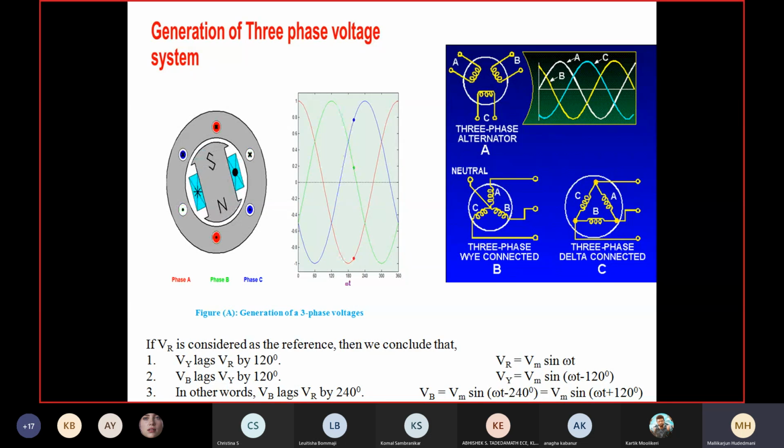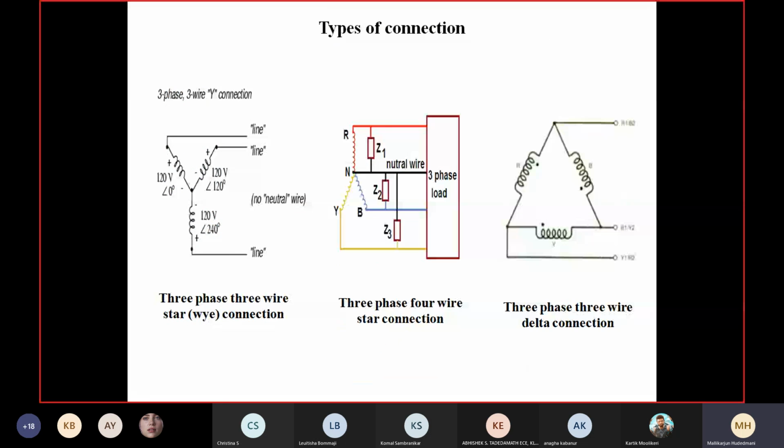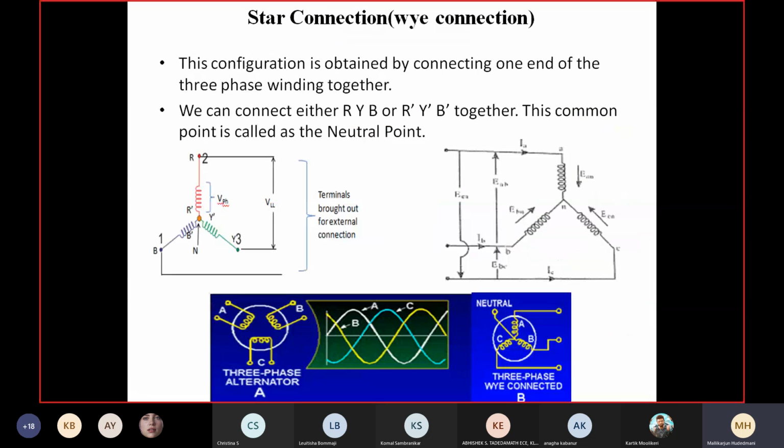That is what we want to know vectorially in today's class. That would be one good question. Explain three-phase star connection and relate line and phase quantities. Explain delta interconnection of three-phase AC. Relate line and phase quantities with the aid of vector diagram. That would be a question.